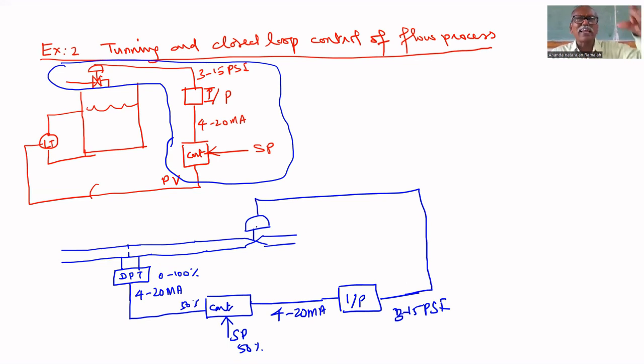So the valve is like the tap at your home. In the tap, you have to rotate to adjust the flow rate. Here, we have to give a pressure signal that varies from 3 to 15 psi, so that the flow rate will vary. The flow rate coming out of this will vary. That's all. This is the flow process. This is the conventional flow process. But in the lab, it is slightly different. Here, the problem is, how the flow rate is adjusted here.